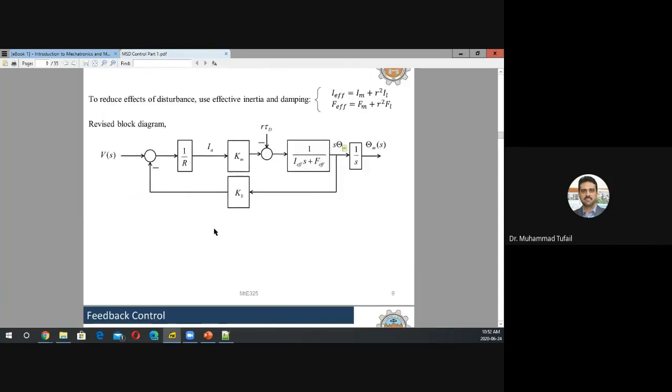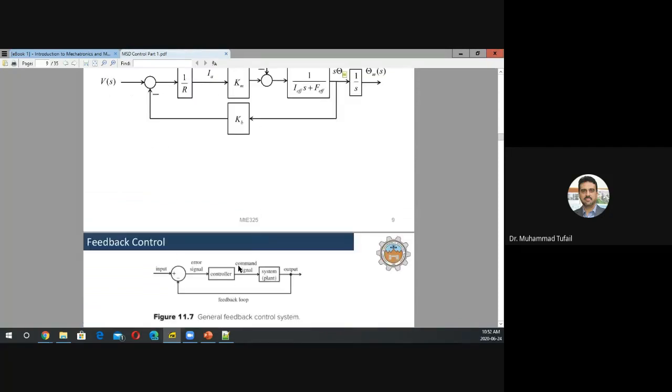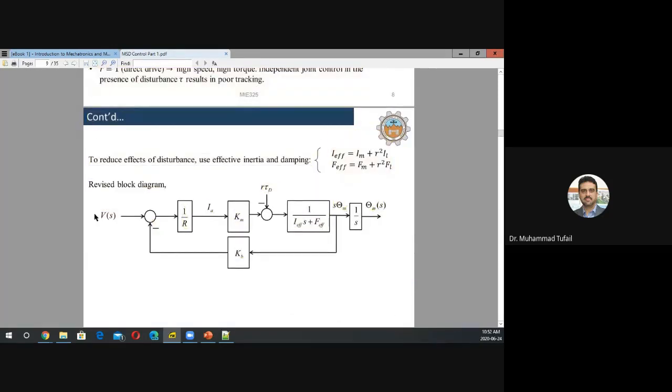Remember, this is all hardware. ये भी armature का है, ये भी electromechanical system में DC motor. Now we're cutting this here. Our V starts from here. Now the output of that controller will be the input to this system. So the input to this system is voltage. So the output of that controller should be the voltage. Okay? Imagine your PWM. So now you'll play with the duty cycle of that voltage in order to get a different response from this, because the response of this system depends on the input to the system.